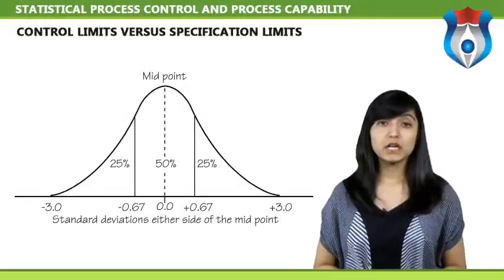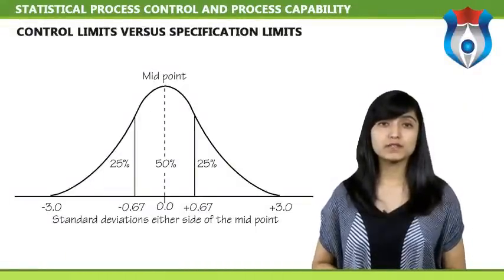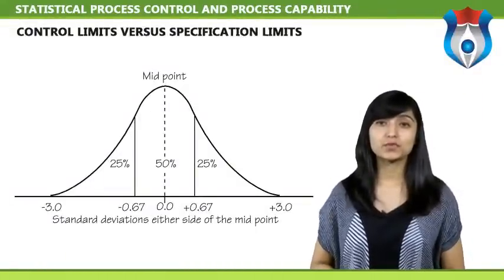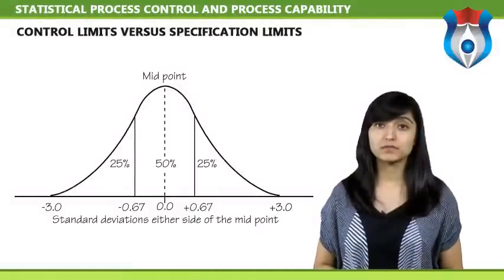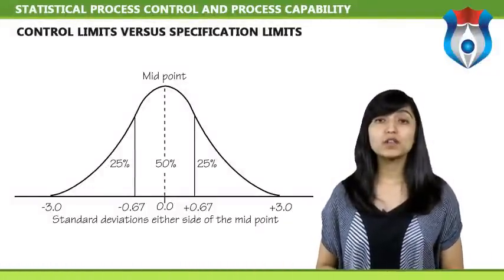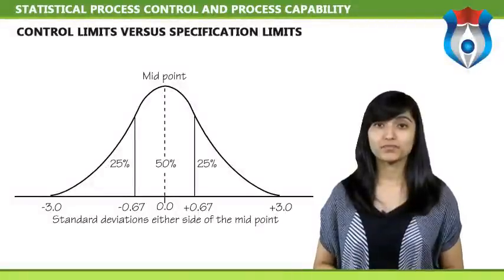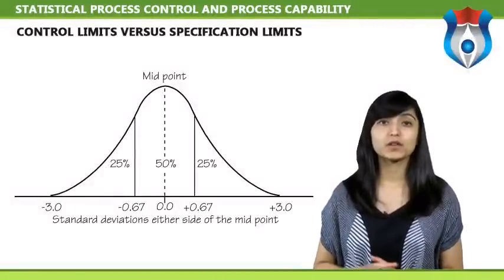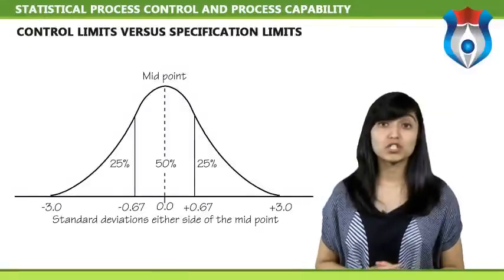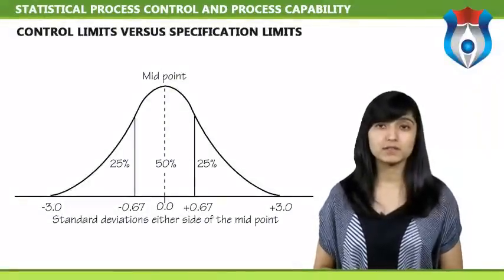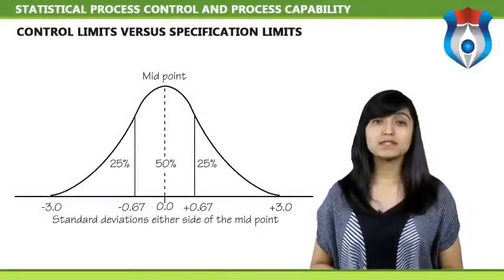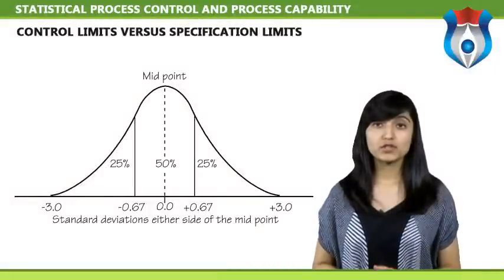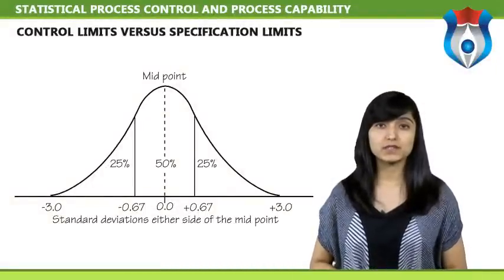For example, if we are filling cereal boxes, our nominal is the net weight printed on the box. We do not want to give away free cereal. But on the other hand, we know variation is everywhere. And if we aim for that net weight, we are likely to get some that go under the marked amount, which can lead to substantial fines. In that case, our process target is higher than nominal so that we do not have any boxes under the net weight.